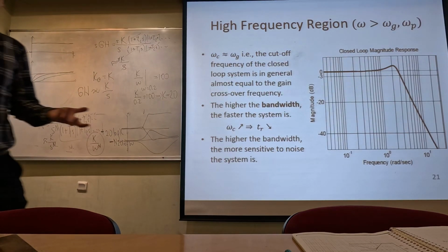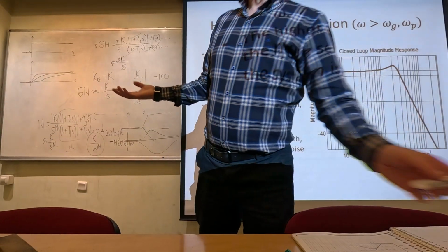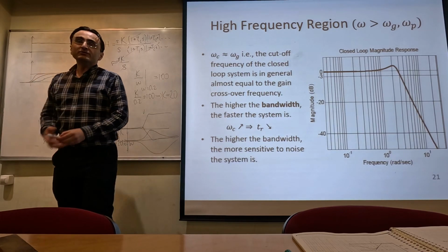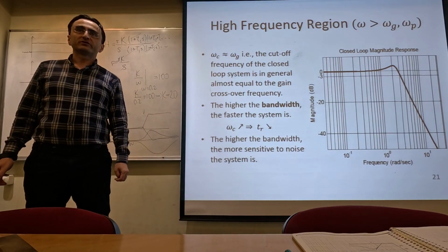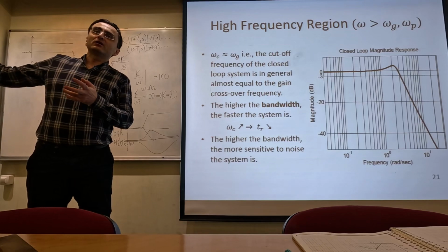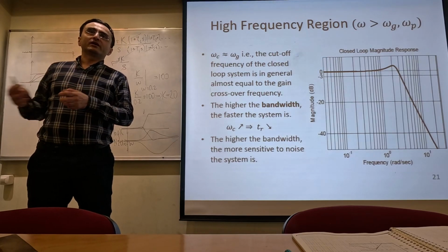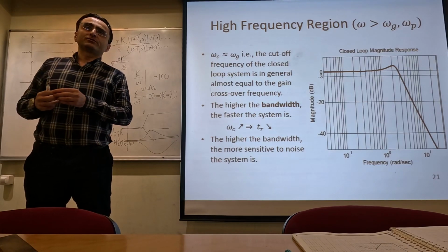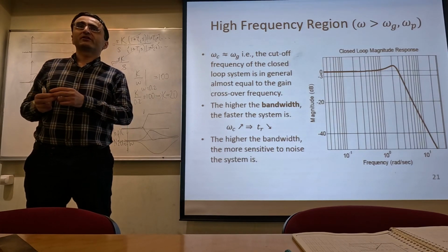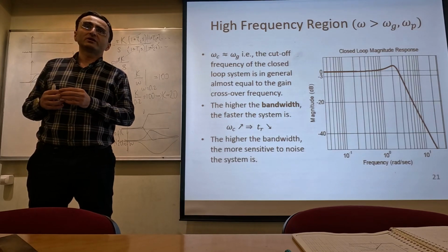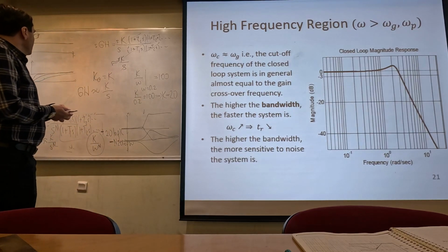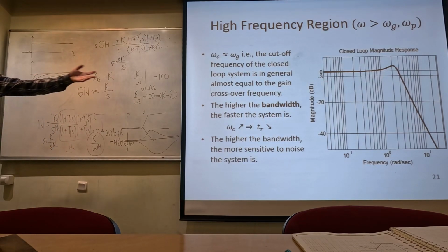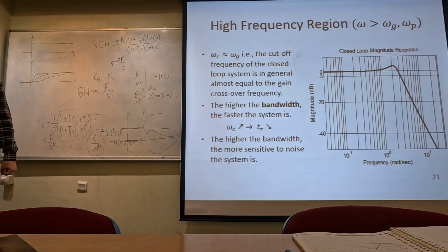So in general, for making our control systems fast, we want to increase the cutoff frequency of your system. But in general, because there is noise in the actual, real system, increasing the cutoff frequency makes your control system susceptible to the noise inputs. Okay? So if increasing the cutoff frequency is good, then I can have as large a cutoff frequency as possible.